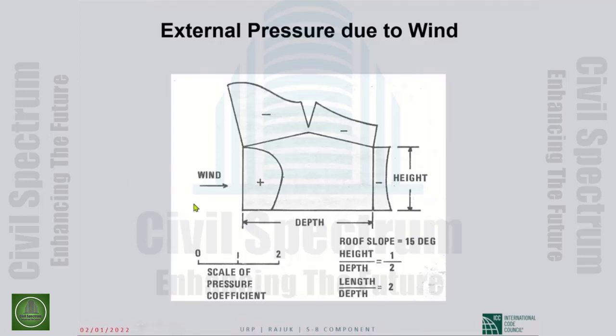A building looks really like that, residential buildings. And at that corner, look at the suction. Huge suctions develop at that corner of the windward face and the windward roof. And unless the roof is held down sufficiently, the roof is sucked up by the wind.